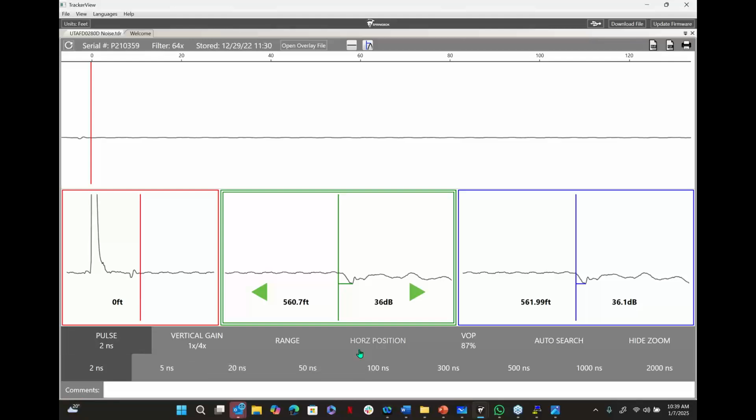So another one of the things I want to point out with a TDR, so we have a basic understanding of pulse widths. I do want to point out for those of you that are using the Springboks and why this is a definite advantage, a couple things I want you to understand. I want you to use 1,000 feet as your guideline for what I call long cables or short cables. Anything under 1,000 feet is what I call short distance testing. Anything over 1,000 feet I'm calling longer.